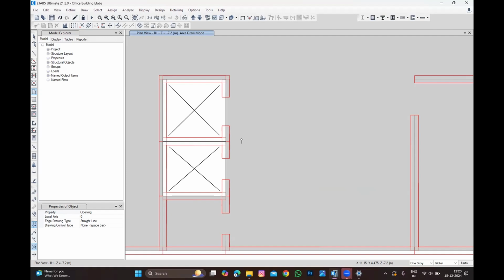So far, we did not eliminate modeling the slabs, to reduce the reinforcement a bit. We used to always model the two staircases. If we don't model it, what will happen? Definitely it will lead to a difference, not in terms of vertical reinforcement but in terms of shear reinforcement, every floor to floor.